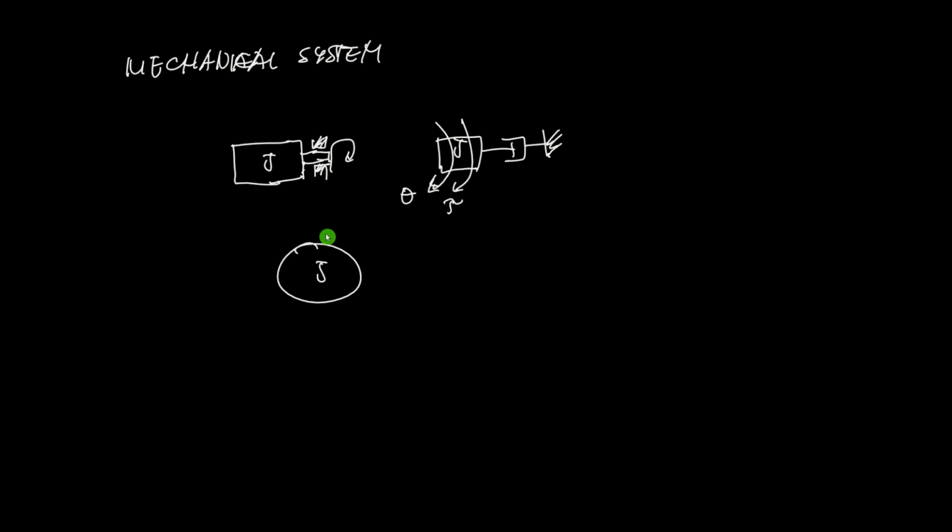Theta is going in that direction, and we also have our torque in that direction. And what else? We have the resisting parts. We only have KD, the damping constant of the damper, and it will be in the opposite direction, the torque due to damping. We don't have torque due to a spring. So from here, apply our concepts in rotational systems.